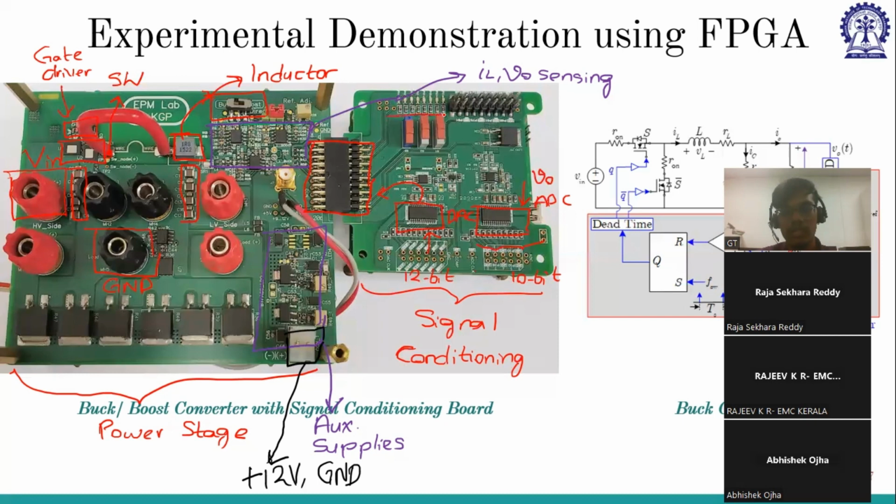And here you can see there are three switches. These switches can be used for giving transients. So we can write a code in such a way that when the switch is off, it is operating at light load condition. When the switch is on, it is operating at high load condition. And maybe this switch we can use for reference transient. So when the switch is off, it has low output voltage. When the switch is high, it will have high output voltage.